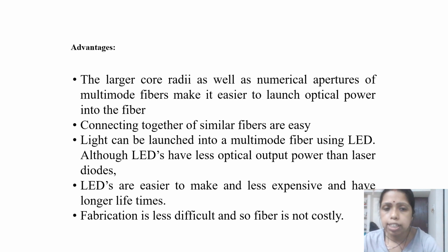There are some advantages. You can easily launch the light through LEDs, because the diameter is large, right? So the LED is one kind of light source. Using an LED, you can easily launch light into the multi-mode fiber. The fabrication is also easy for multi-mode fiber, and it is less costly. The LED is also less expensive in the case of the multi-mode fiber.